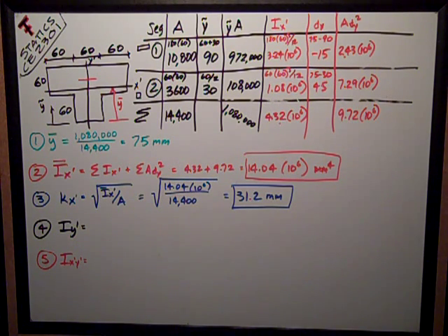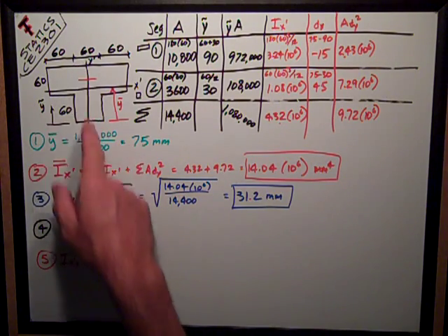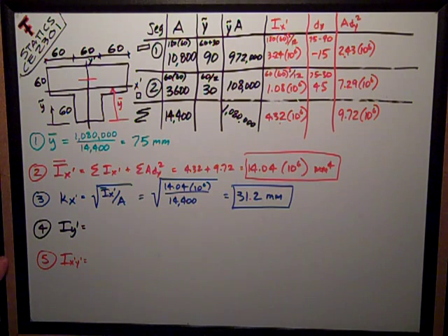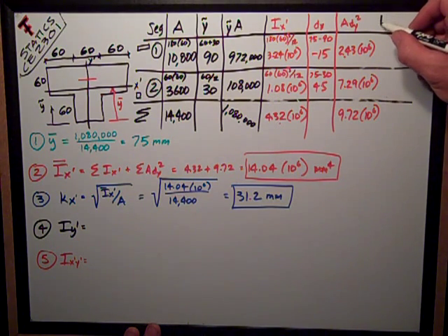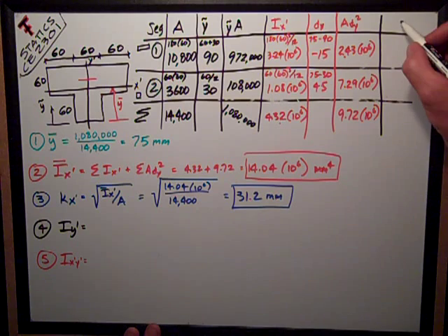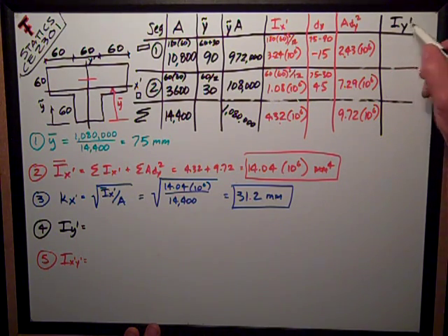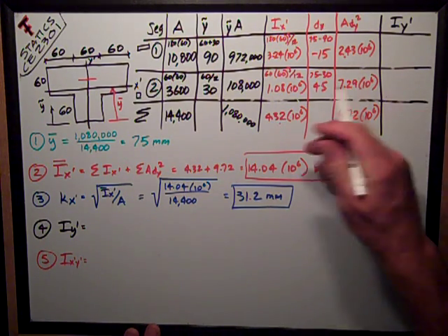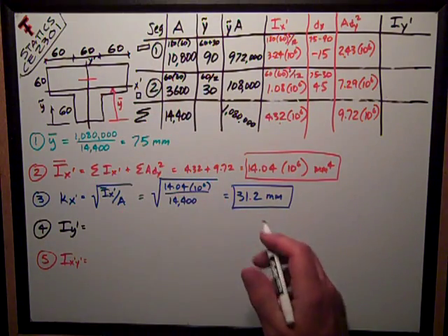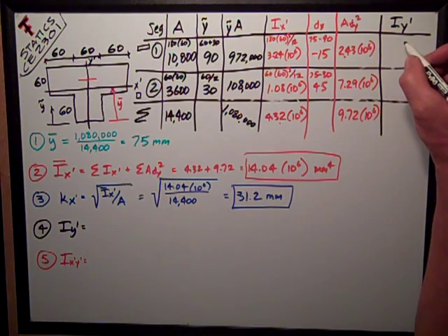The fourth problem is what's the moment of inertia about the centroidal y-prime axis, the vertical axis. And I don't have much room here, but I think I'm going to be alright because of this one fundamental thing. I'm going to first compute my centroidal moments of inertia, Iy prime, which are just bh cubed rotated, or hb cubed if I consider this orientation.